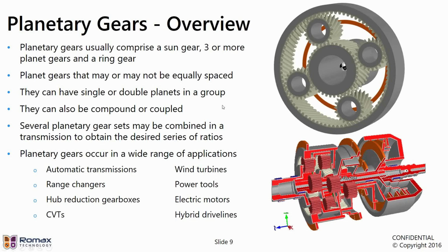In addition, you can have different combinations of these gears. So here we can transfer torque from the sun via a planet to the ring, or vice versa. But equally, you can have pairs of planets in there, so it could go from the sun to the planet to another planet and then to the ring, for example. It's sometimes called reversing planetary gear sets.